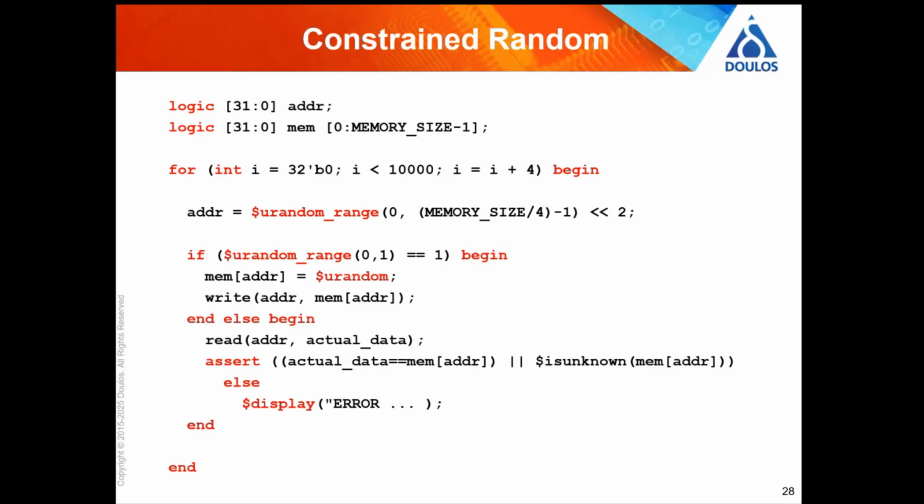If you think about it, an array is just like an abstract high-level model of a memory. Memories have address buses and write enables and low-level stuff. They're made out of transistors. But an array is just at an abstract level the same thing. And so the array is the model, and you can see on that assert statement at the bottom that we're effectively comparing what came out of the design under test with what is coming out, in bunny ear quotes, of the reference model.